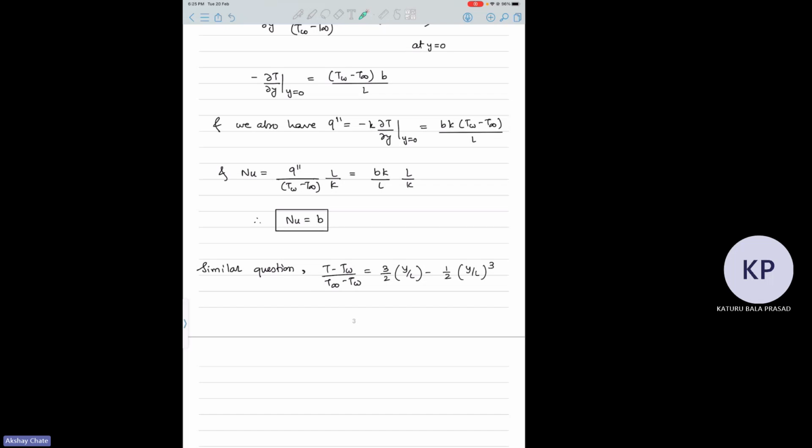Typically, it's not mentioned here, but this Nusselt number, in this case, came out constant, but as you can guess, it will not always be constant. We'll discuss this in the next class, but what they typically do is some experiments are done for certain sets of boundary conditions. Not initial, only boundary conditions, because we typically deal with steady state problems here.